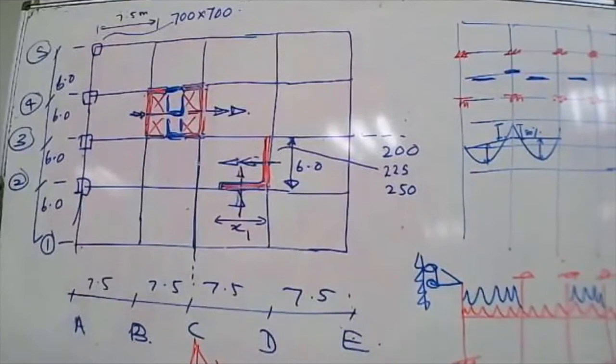So if you send the beam reinforcement into the wall, there's very little chance for it to fail. Because of that, we will not worry too much about this connection, because we consider it a proper connection. The answer comes from the fact that we are going to provide sufficient reinforcement in the beam so that it can be properly connected to the wall. So I don't anticipate any problem there.